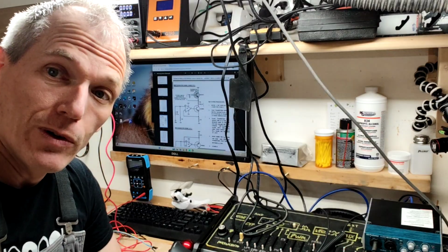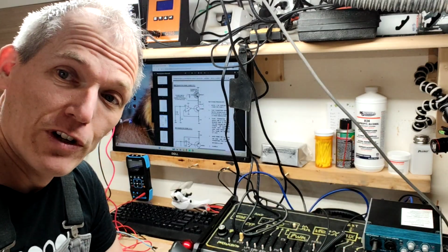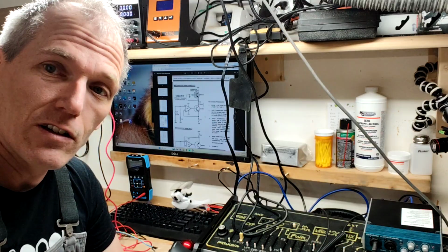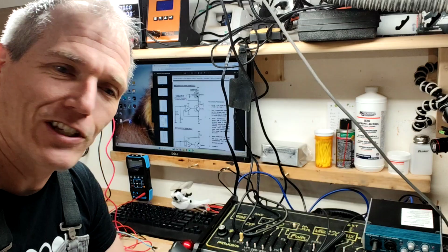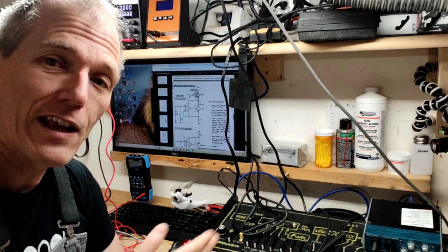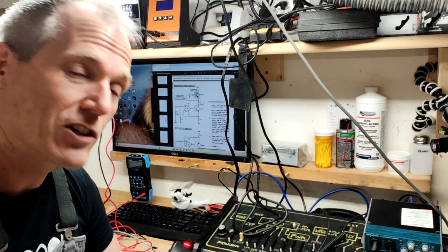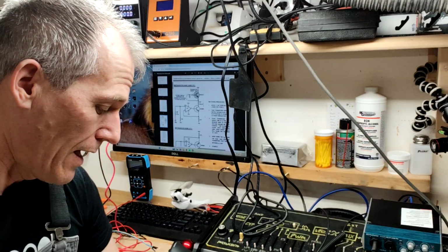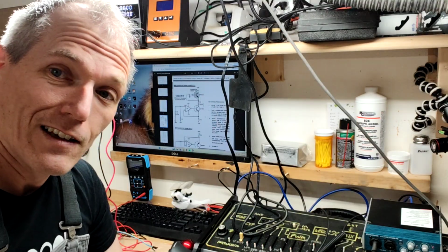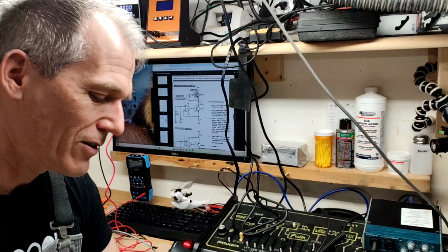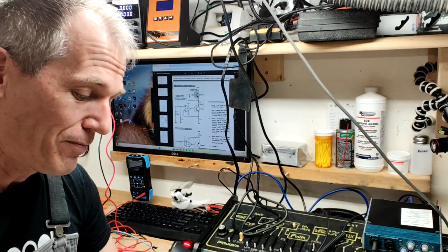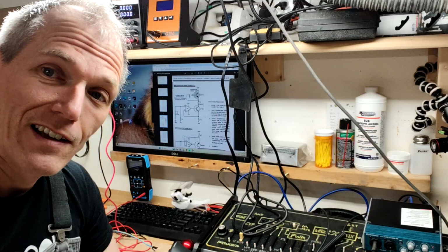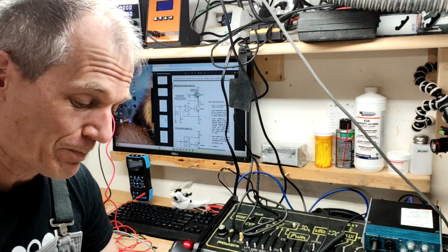So the next thing to do here is probably find some matched transistors and build that circuit that just exponentiates the current, exponentiates the voltage, so that we can have a current that's proportional to the exponential of the voltage. And that will feed into the oscillator, the first part of the synthesizer. Wow, there is a lot to go. But this is going to be a great journey, and I hope you join me on it.